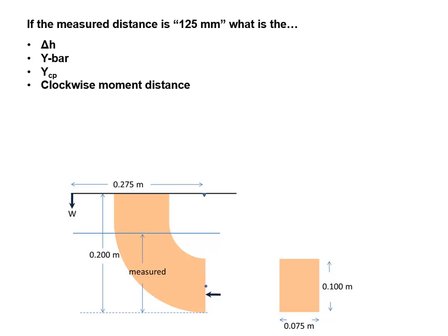And so that distance of 0.13 plus 0.04667, that moment distance is 0.17667 meters. So we multiply the ratio of the moment distances by the force that's located at W, which was 1.12815 newtons. And that would tell us that the actual hydrostatic force was 1.756 newtons. And that's actual hydrostatic force.